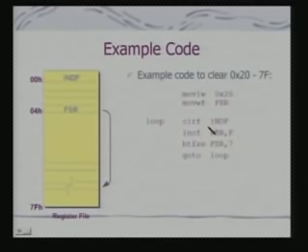It will take place because I am clearing INDF. INDF is an indirect addressing register. That means, when I am trying to clear INDF, it essentially means that the register memory location pointed to by FSR should get cleared. Is this clear?